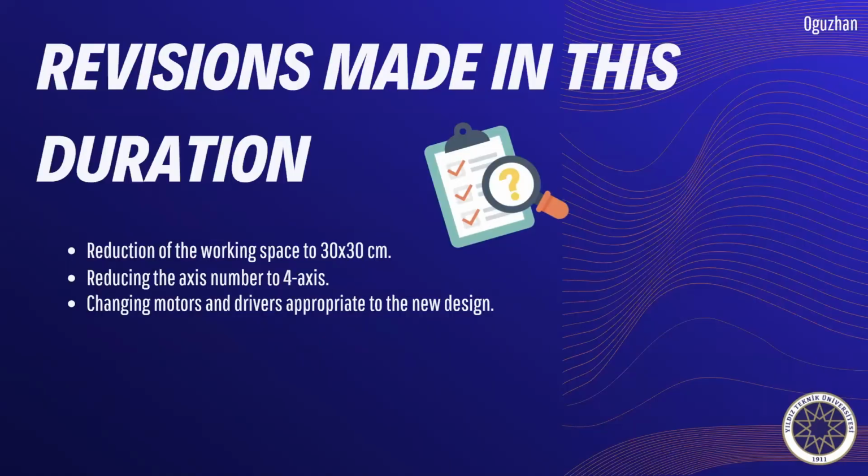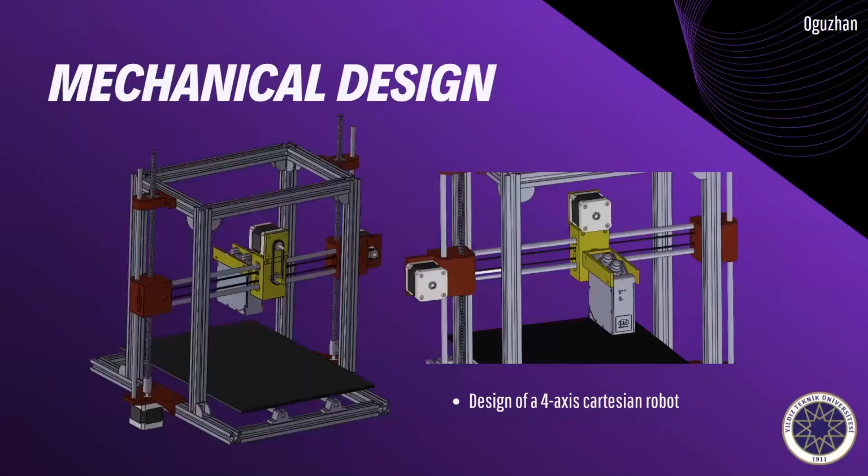After the mechanical system design course, some changes had to be made in our design and technical requirements. First of all, the workspace of the robot was reduced to 30 times 30 centimeters. Also, the axis number of the robot was reduced to 4. Due to all changes, motor and drive wheel calculations have been made and new components are chosen. Here, our new mechanical design can be seen.